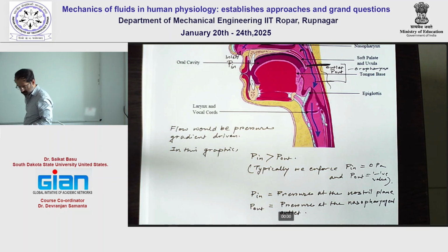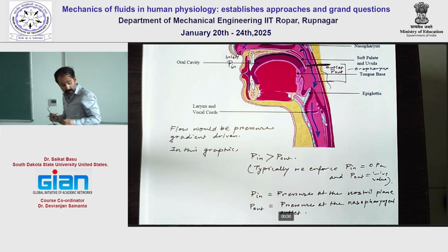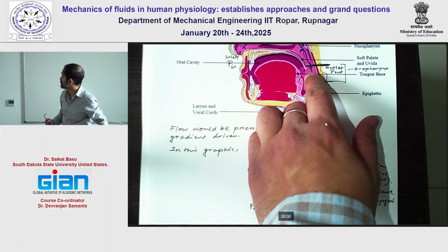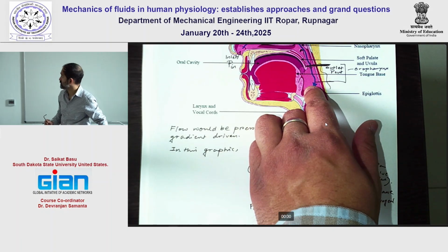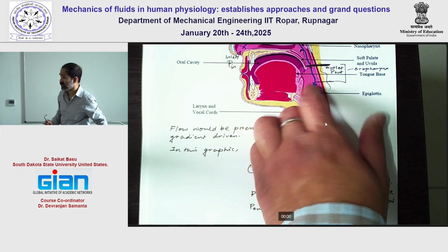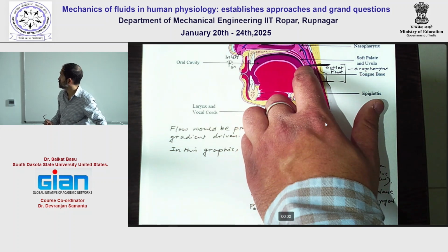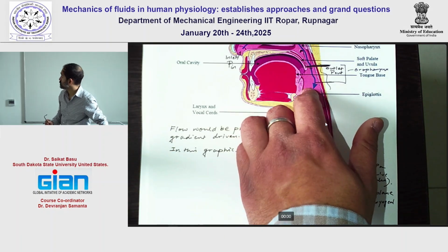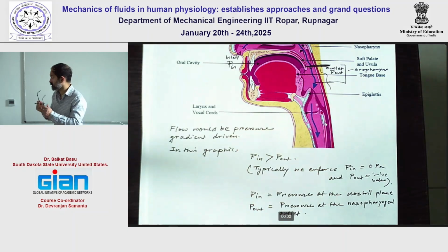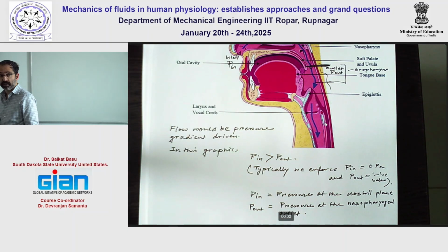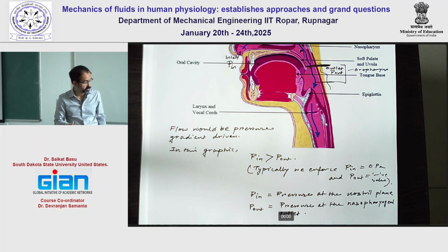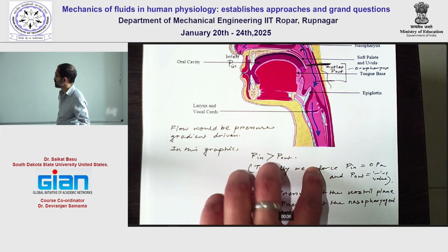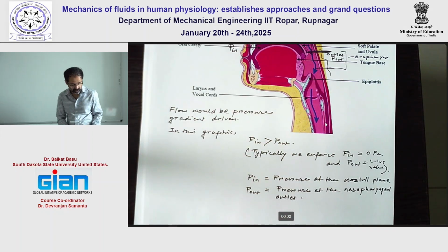The geometry that I think is shared with you guys, the anatomical part ends over here at the base of the nasopharynx, but after that I have included a straight tube that goes vertically down, just to make sure that the flow is well developed at the nasopharynx and we don't come across any kind of end layer effects over here. So that straight tube that you will see is not anatomical. It is just to make sure that the field is well developed at the nasopharyngeal airspace. But if you are doing something further downwind, of course, you need to include all the other details of the anatomy.